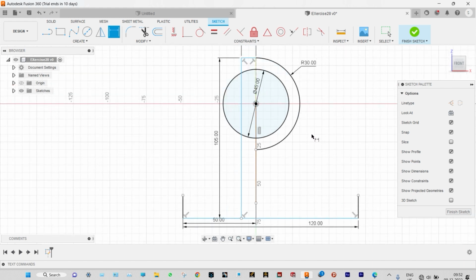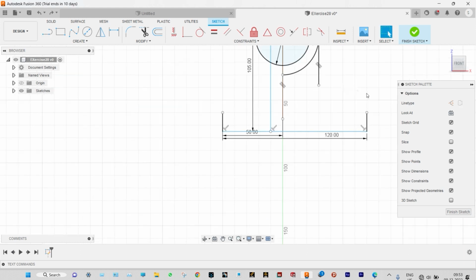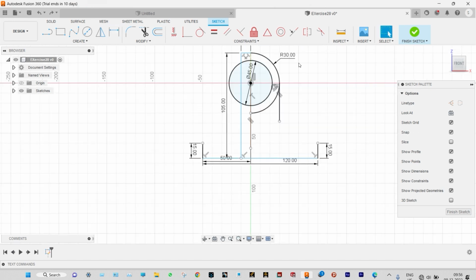now we need to create some lines. You can drop a line from here at any arbitrary length. We need to provide the dimension of these lines. Let us provide this one to be made up of 15 mm. Done. Again this one also 15 mm. Done. Now we need to provide a smart dimension from here to here. This one will be 75 mm. Done. Now we need to create two more arcs which will be tangent to this line and this line again,